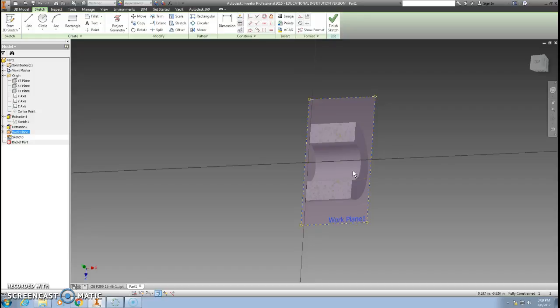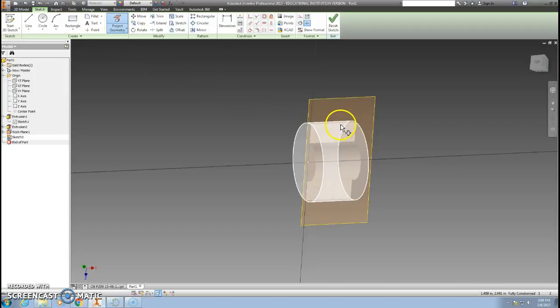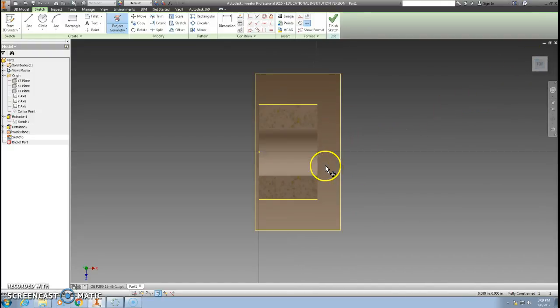If you look in the book, you'll see that the elliptical shape needs to be 1/2 inch thick, and it's going to go out to the quadrant of this piece. So I need to project my geometry for this, and I'm going to look at it from the top view. So I know that is the length of my cylinder. I'm also going to maintain the 1/2 inch thickness through there, and I'm just checking here the dimensions that they give us in the book. You'll see they want the elliptical shape to be 1/8 inch from the right hand side.